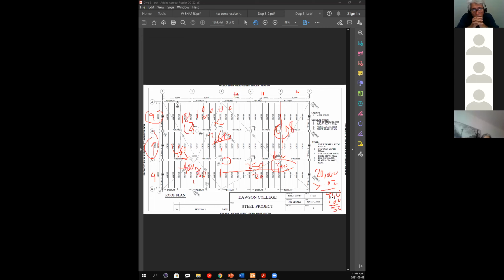What would be the value here at the end? It would be 100, right? Yeah, exactly. You always want to drop by at least 100. Whoever did this drawing, I penalized her by not putting minus 100 here. Because you want to make sure that the joist sits on top of the beam, and this whole steel has to be dropped by 100.